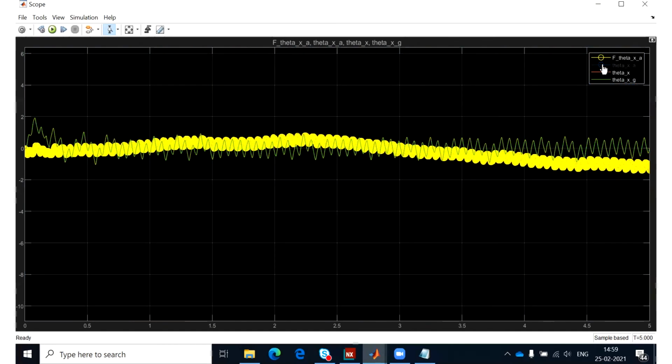After filtering that, you see that it helps a lot. In reality, the IMU sensors also have an internal filter, and when you get the data from the sensors, it is already filtered, but you can add another filter to that if it is not filtered enough. So you can improve the filter. So this is what you have.